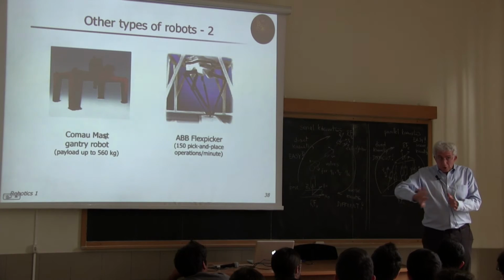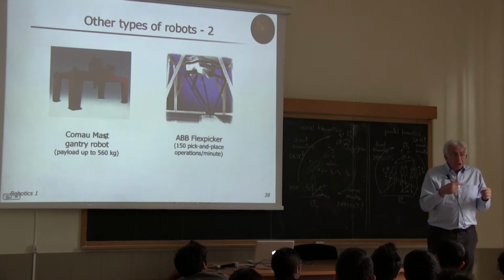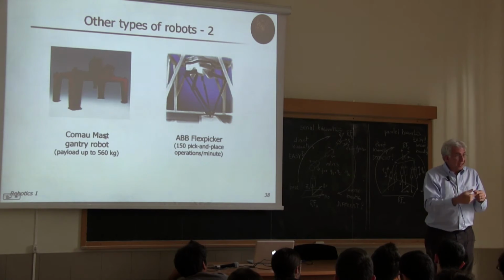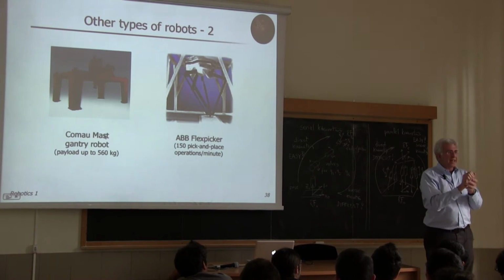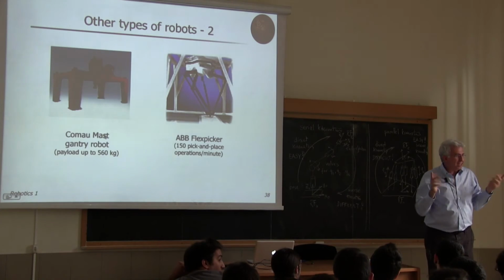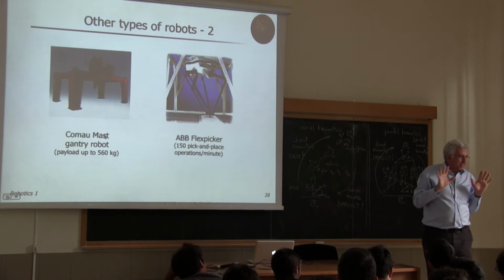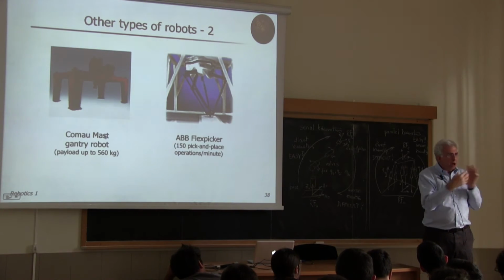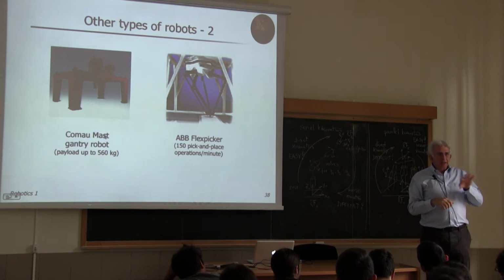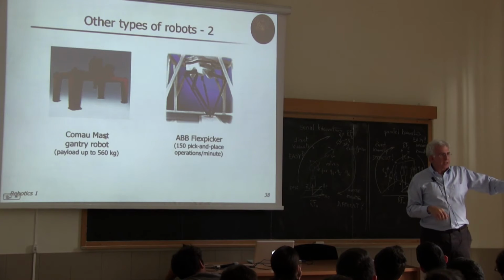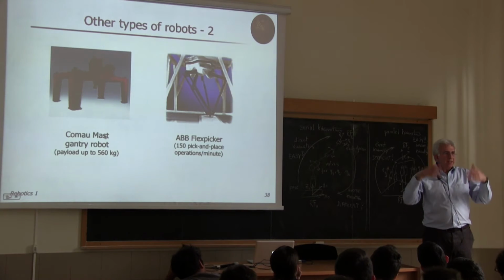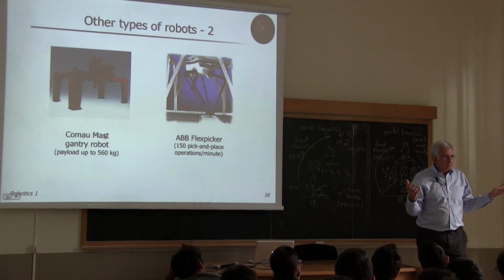We have left open the point of denoting what is the series in these three, because we know that we can rotate around this axis, around this axis, but which axis comes first, we don't know yet. This depends on how we will model this. But in fact, let's take out the spherical wrist because this is serial. Now what is left is the three prismatic joints.